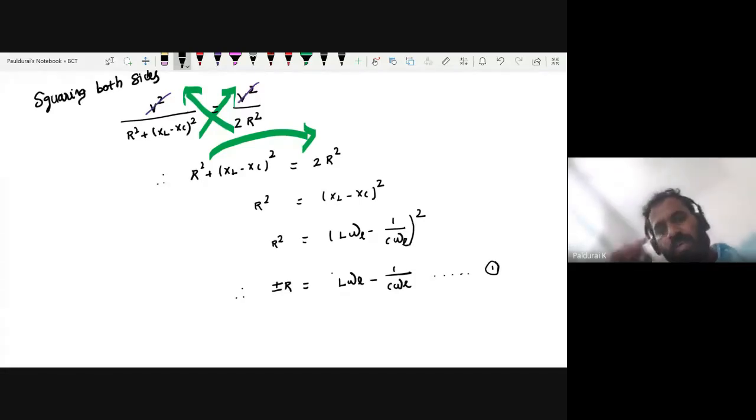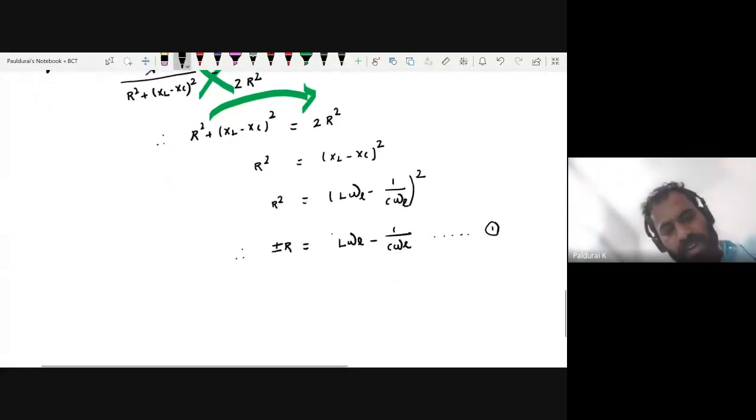Okay. Now listen. At FL, at lowest frequency, who is dominating? XC dominates XL or XL dominates XC? XC is greater than XL.